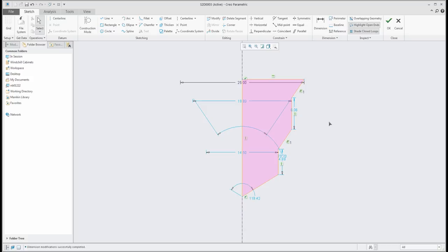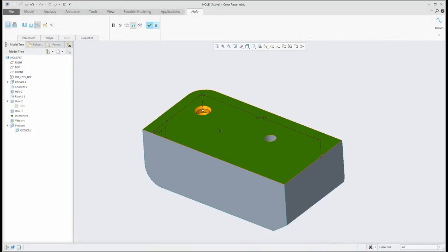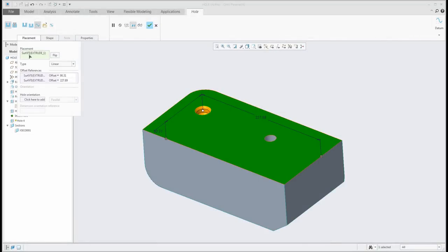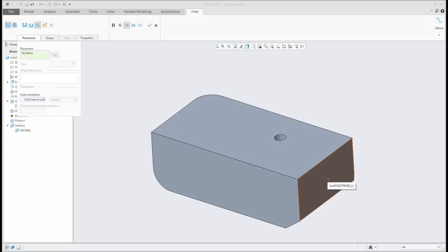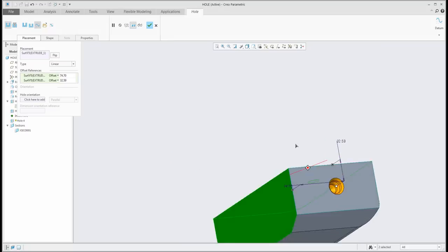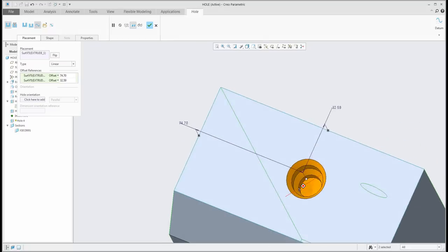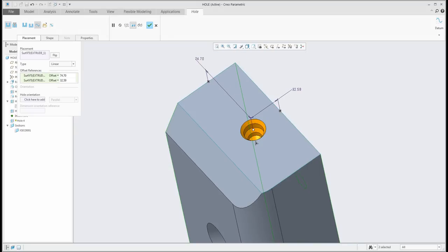What is necessary to do for this sketch is that the horizontal line is placed on the top in the sketch, and that horizontal line is placed directly on the placement surface. So for example like this, or if you change the orientation, I will remove everything and I'd like to place this hole here. The system will create the dynamic preview and specify it for me.